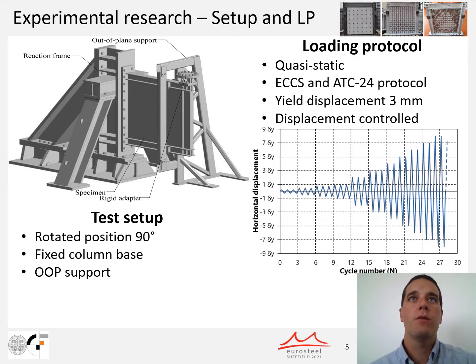Due to vertical placement of the actuator, specimens were rotated by 90 degrees from their true position within the structure. Specimens were bolted to the supporting reaction frame, which simulated a fixed column base. Simulation of the out-of-plane support was carried out using a lateral bracing truss. Loading of the specimen was carried out from one side only using a rigid adapter.